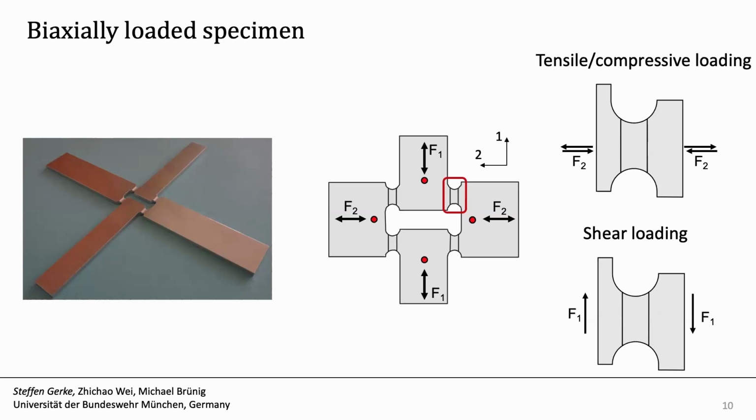And if you load this axis 1, you get shear stresses in the notches. So you can superimpose tension with shear or compression with shear, and you can change during the experiment. So you can really do a lot of different loading paths with this geometry.